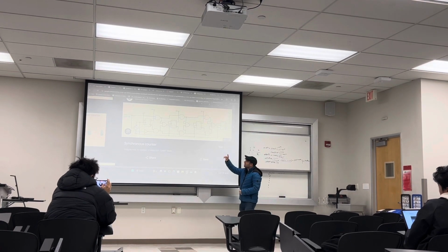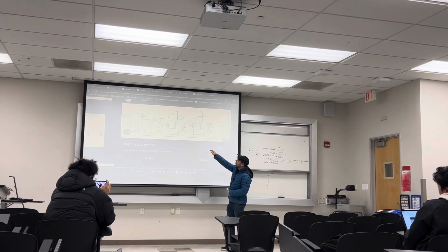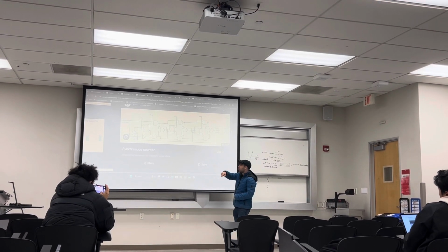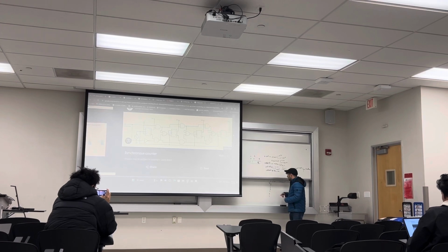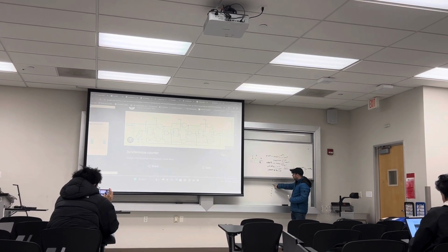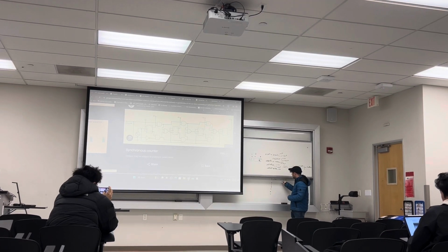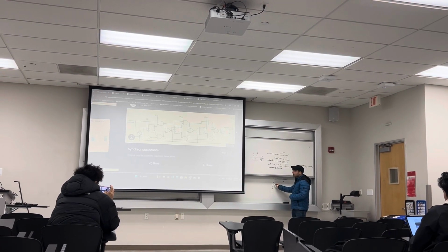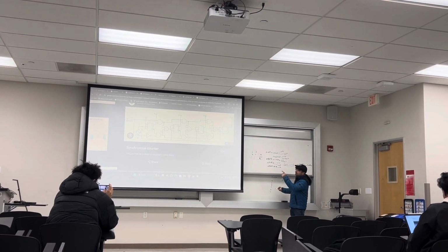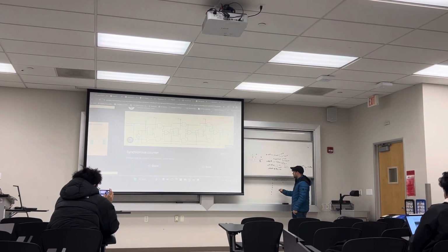So the second JK flip-flop only changes when the up and down is 1, and also the first JK flip-flop output is 1. So look, for example, if the first JK flip-flop output is 0, the second one will stay 0 also. When it's 1, the output must change. But there is one delay between these two, because there is one step after the first JK flip-flop.